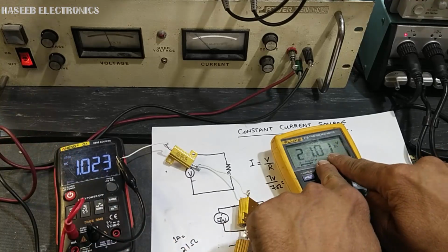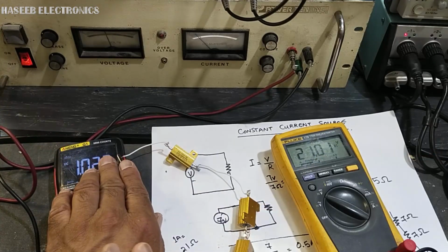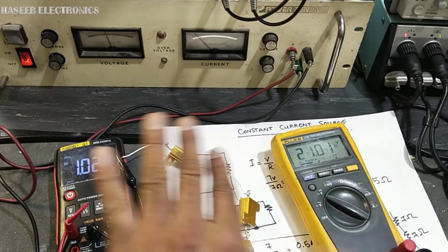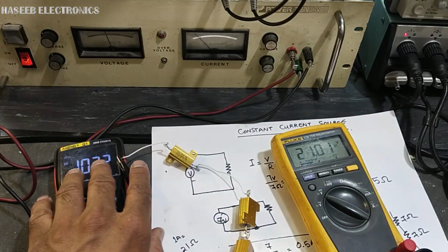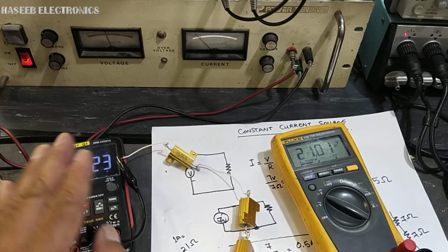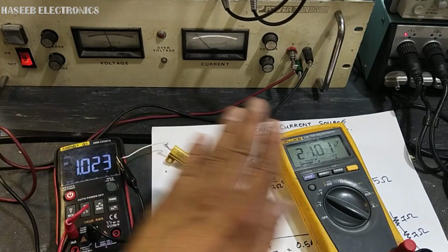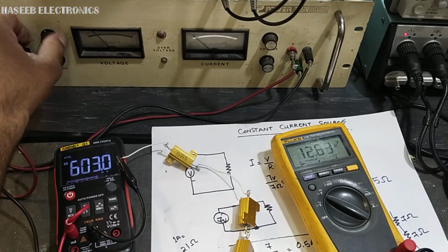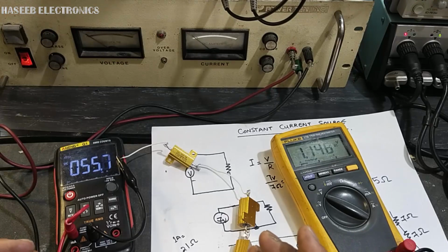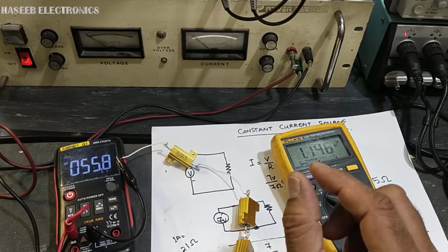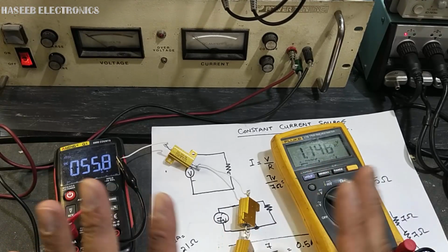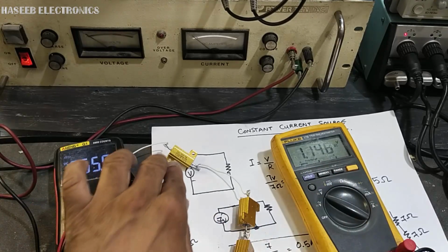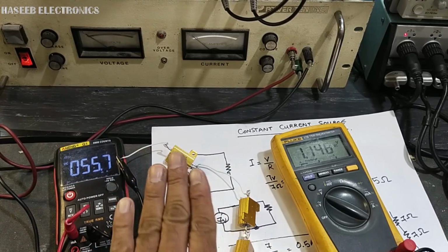At that time it will follow this 1 ampere. It will not take care of the voltage. An ideal voltage source or constant voltage source will maintain its voltage. It will not take care of the current. But a current source will monitor the current. As we see in inverter welding machines, when we set a current, we are not monitoring the voltage. It will monitor the current flowing through the electrode. The same here.